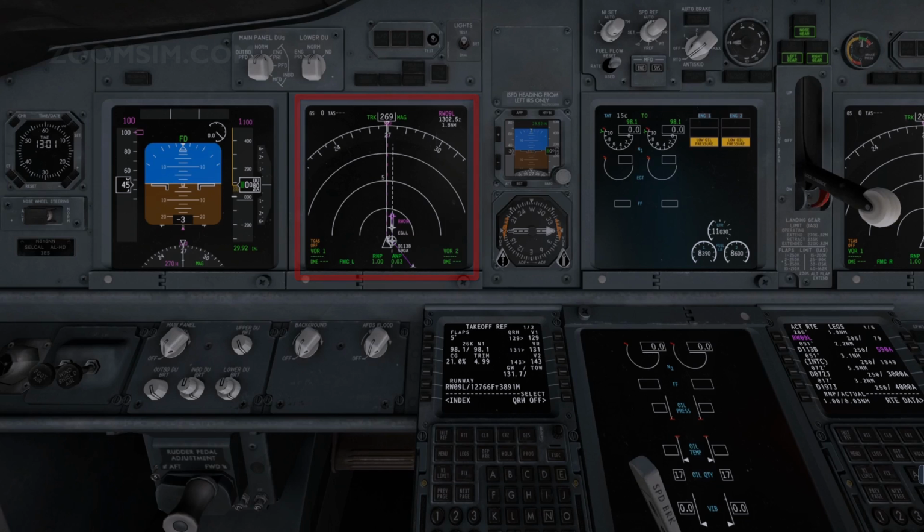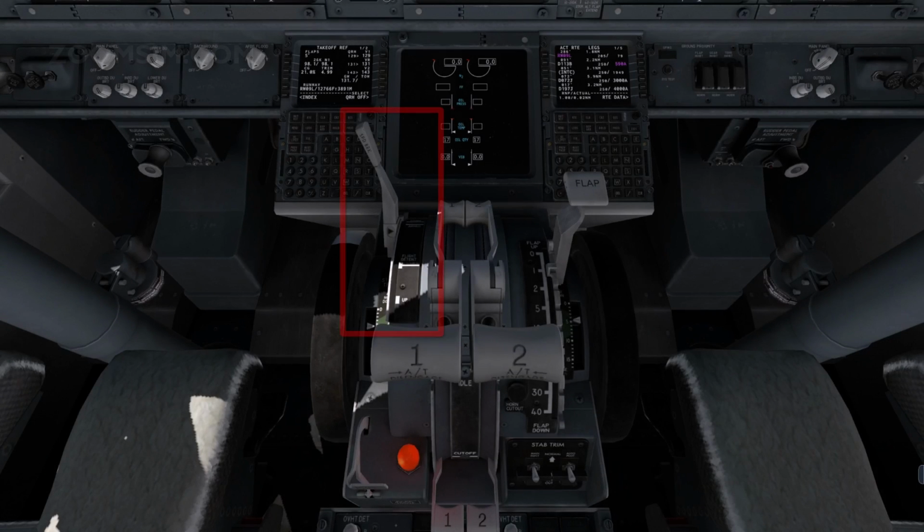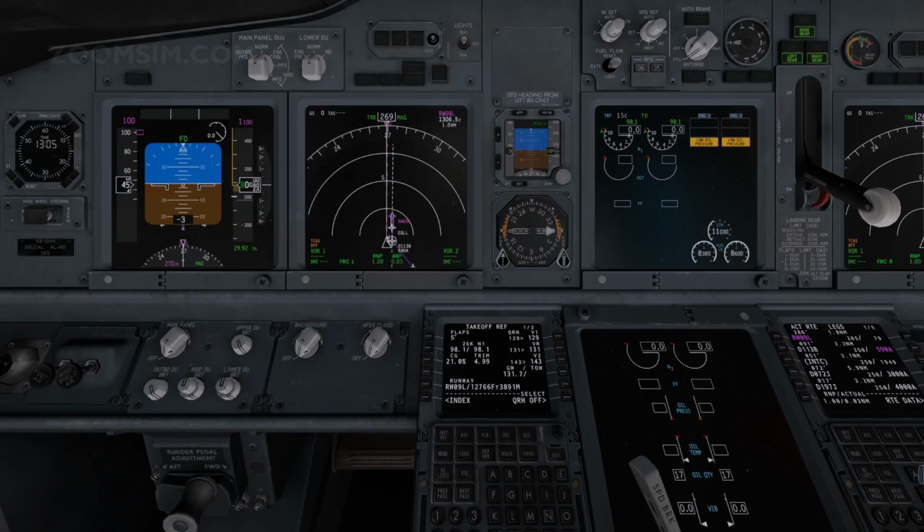Expected RMI flags. Verify that the flight mode annunciations are correct. Auto throttle mode is blank. Roll mode is blank. Pitch mode is blank. AFDS status is FD. Select the map mode. Speed brake lever, down detent. Verify that the following lights are extinguished: speed brake arm, speed brake do not arm, and speed brakes extend.